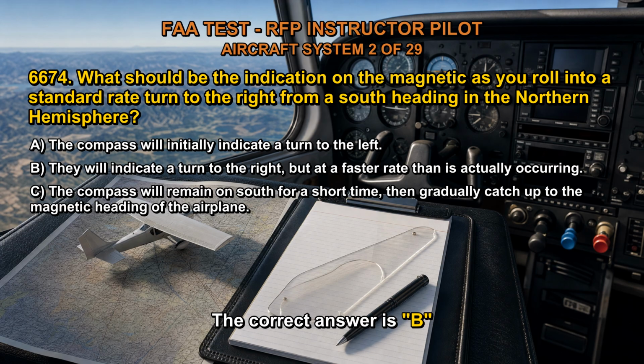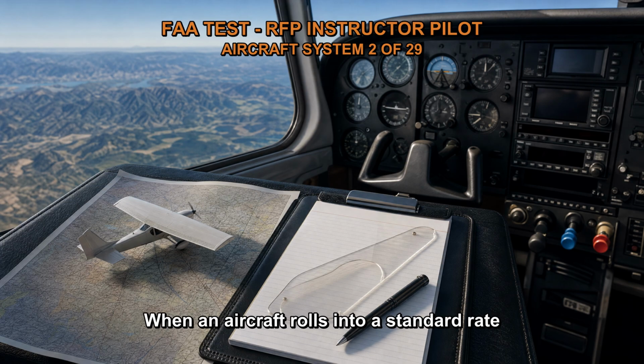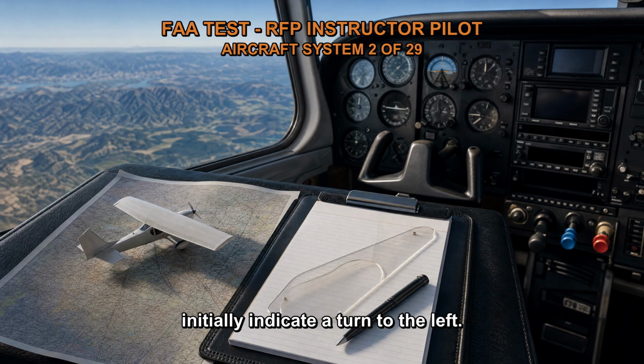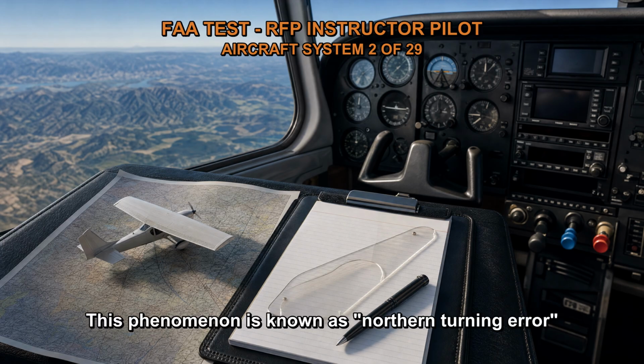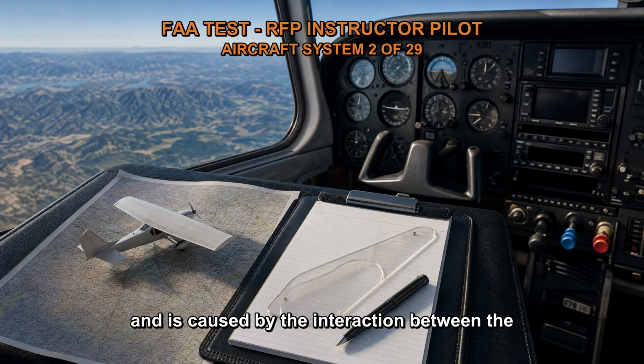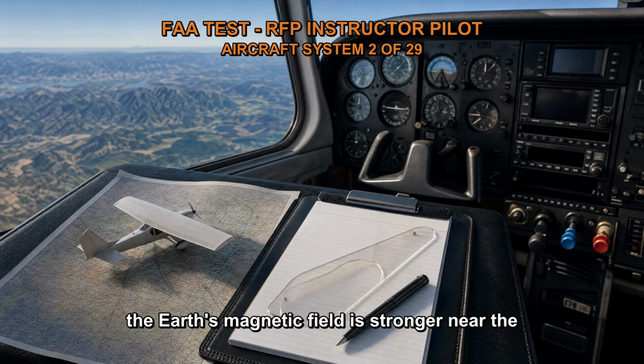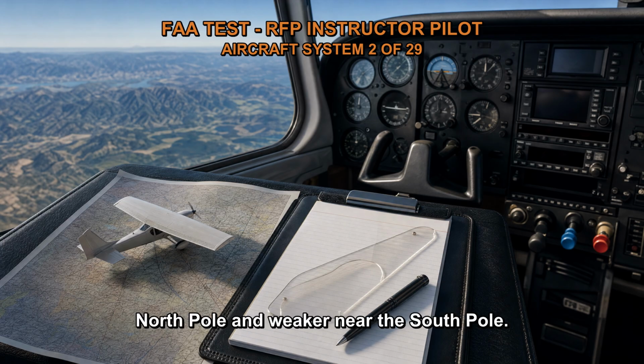The correct answer is B. When an aircraft rolls into a standard rate turn to the right from a south heading in the Northern Hemisphere, the magnetic compass will initially indicate a turn to the left. This phenomenon is known as northern turning error and is caused by the interaction between the Earth's magnetic field and the compass card. In the Northern Hemisphere, the vertical component of the Earth's magnetic field is stronger near the North Pole and weaker near the South Pole.